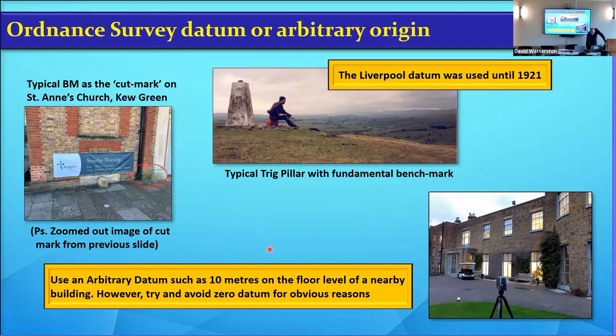So as I said, try not to use the zero datum. And I've had some architects that love that. The trouble is, when you're up in London, they're spending millions doing underground living accommodation, staff accommodation, swimming pools and things like that. And they've given the floor level of 0 because they think it's clever and it suits them.